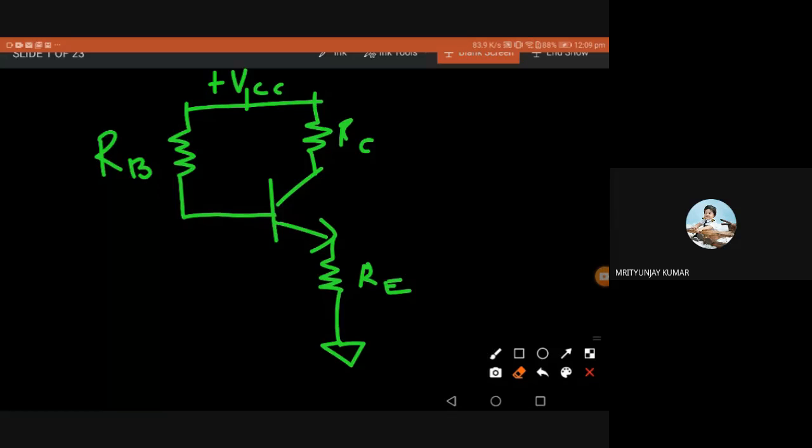Here, we are taking some part of the output voltage or current, and we are monitoring the increase of that quantity, maybe IC here, and based on my output, I'm trying to give the signal back to the input so that I can stabilize the input parameters so that my IC is maintained. If IC is going too high, automatically the output will sense it and give back to the input that, okay, decrease IB. So I'll decrease IB. Again, the IC is decreased. Again, there is some mechanism in the output voltage or current signal which goes back to the input and says, okay, you just increase the IB so that IC is also increased. So some way or the other, the IC is maintained through a feedback mechanism. This concept is very important. We'll be using it especially in the last module, op amp, etc.